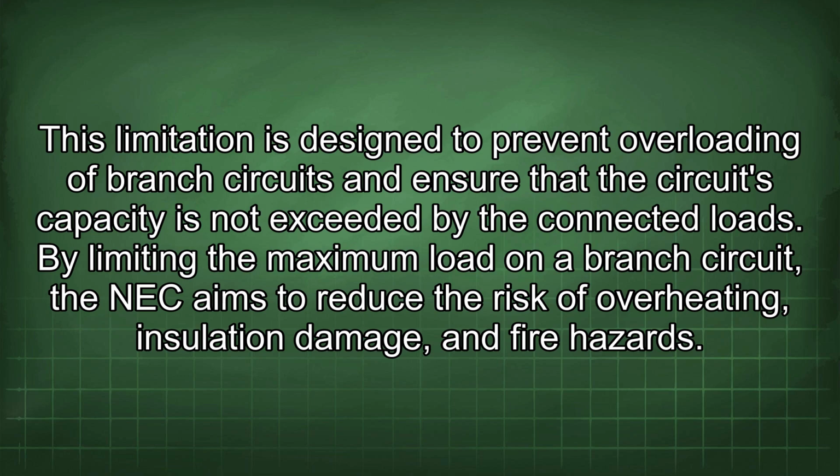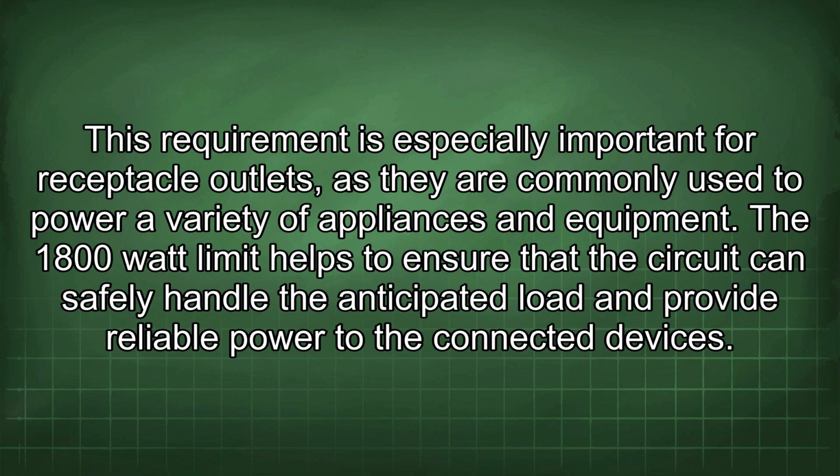By limiting the maximum load on a branch circuit, the NEC aims to reduce the risk of overheating, insulation damage, and fire hazards. This requirement is especially important for receptacle outlets, as they are commonly used to power a variety of appliances and equipment. The 1800 watt limit helps to ensure that the circuit can safely handle the anticipated load and provide reliable power to the connected devices.